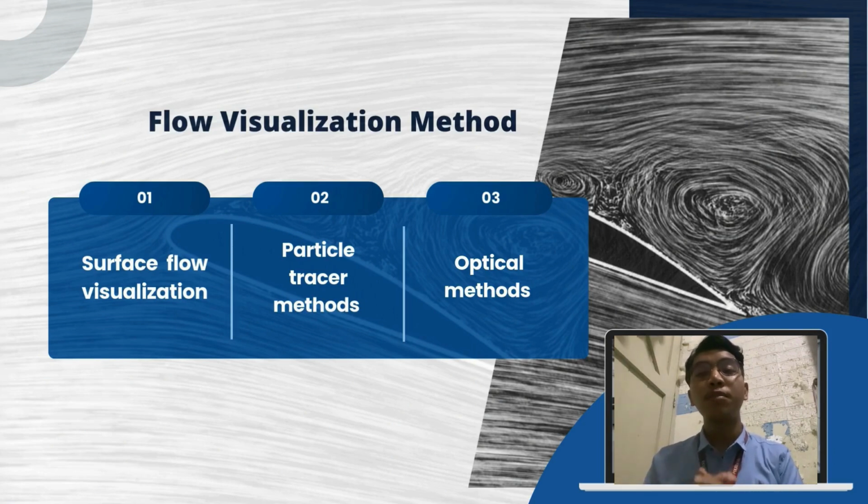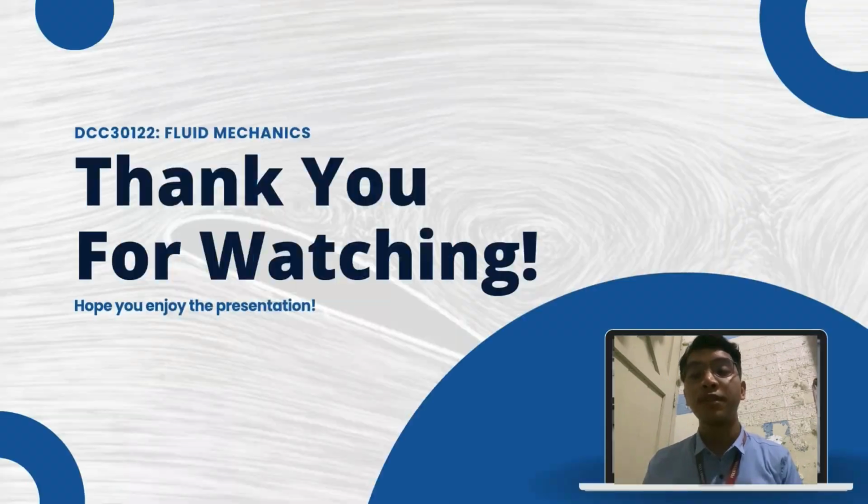Last but not least, optical methods. Some fluid flows display patterns through changes in their refractive index, which can be visualized using techniques like shadowgraphy, schlieren photography, and interferometry.